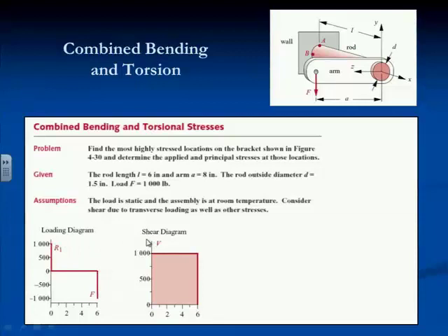The way I used to tell students to figure this out years ago, before we had computers, I would say, imagine you're walking backwards across the beam. I want to draw the shear diagram. You're walking backwards across the beam, and you're going to record in your little pad every force that you see as you walk backwards, okay? So I take one step back, and I see R1. And so I still see R1, R1, R1, R1, R1, R1, R1. And as I step off the beam and go, I see F. And scribble that down before I splat on the pavement, okay? So what you're doing is recording the forces that exist across the beam.